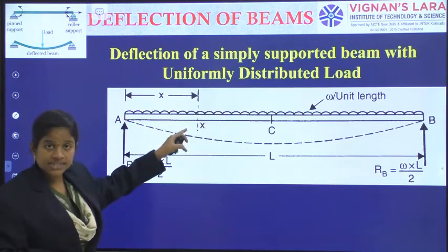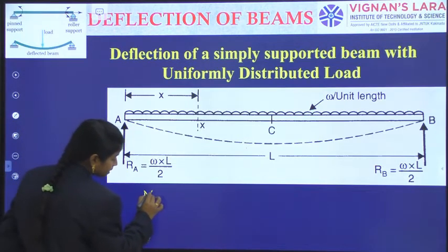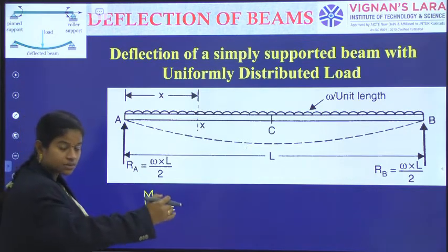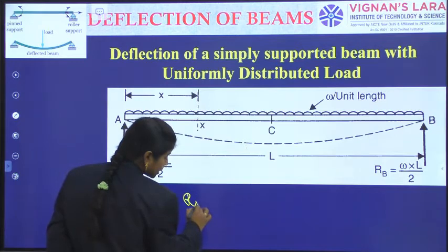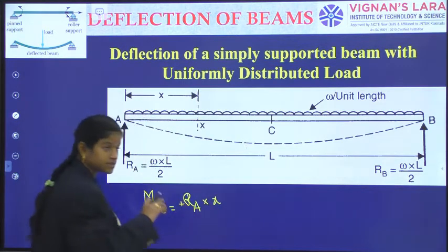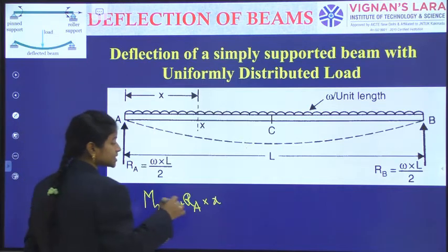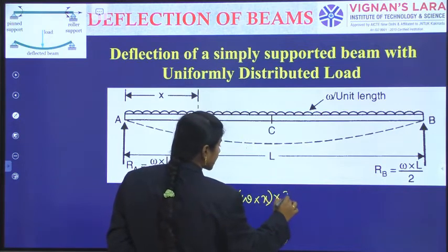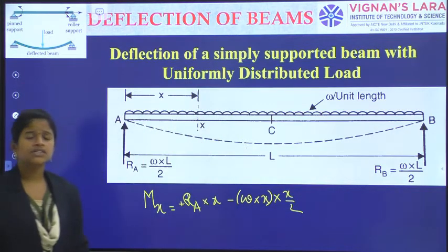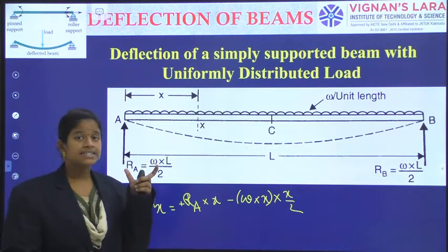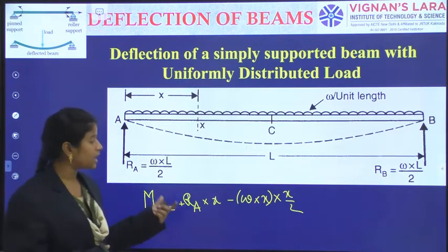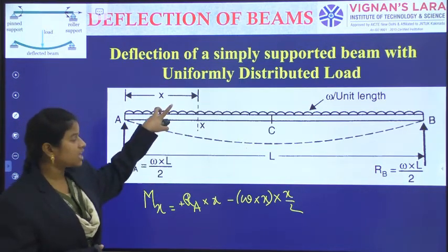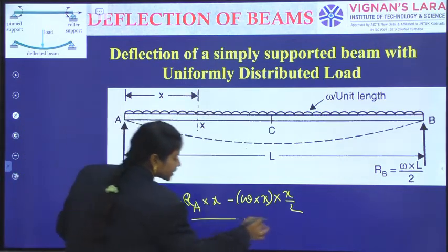Now the bending moment at the section, Mx at this section, is equal to the summation of all the left hand side moments or summation of all the right hand side moments. So I am taking here RA into x. That too is positive. See here it is causing the sagging type moment, and then there is a negative moment of minus W into x, and it is acting at x by 2. Already we have done so many numericals for the UDLs. As x is the length of the UDL, at the center of that UDL there will be application of the load. So W is the intensity of the UDL, so W into x by 2 is the loading application multiplication. So in this way the Mx will come.